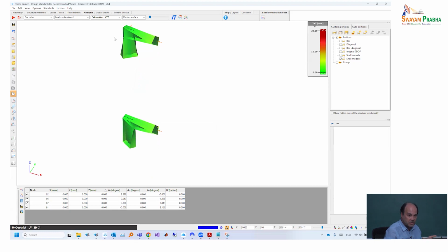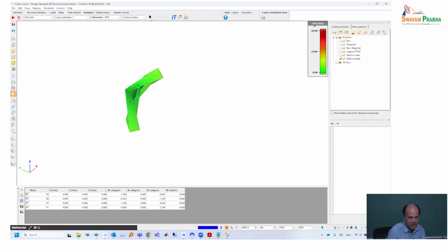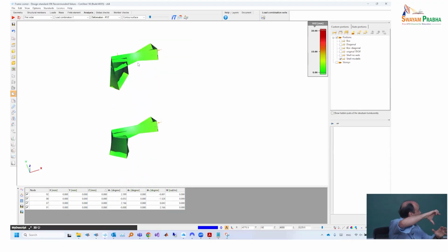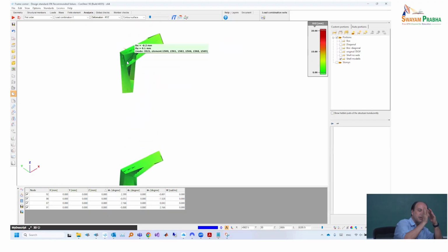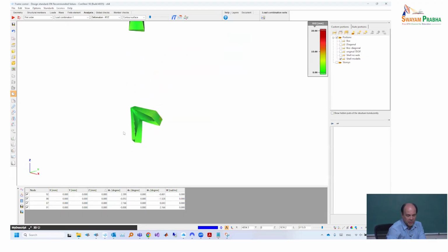Now, in case of the most commonly used solution, it is just the opposite. And why? Actually, this can be very easily understood if you just see that this flange comes into the zone with a certain rotation. That rotation continues into this plate. That plate moves to the right. It's a cantilever, connected to this cantilever, they are moving together. Obviously, when they go out, the other must go inside, and this deformation already happens. This other is already more difficult to explain so easily, but this is a very rigid connection here.